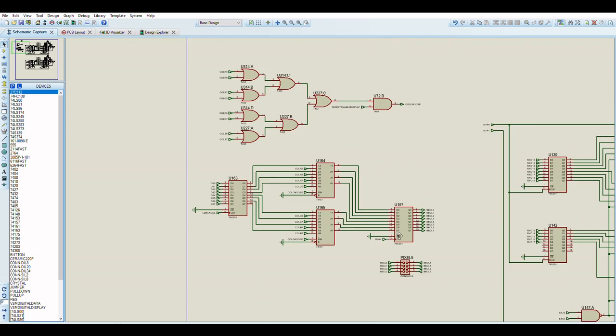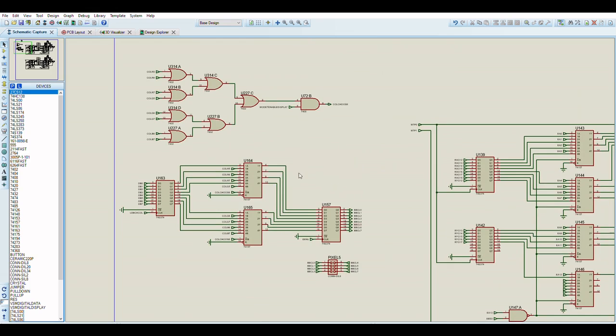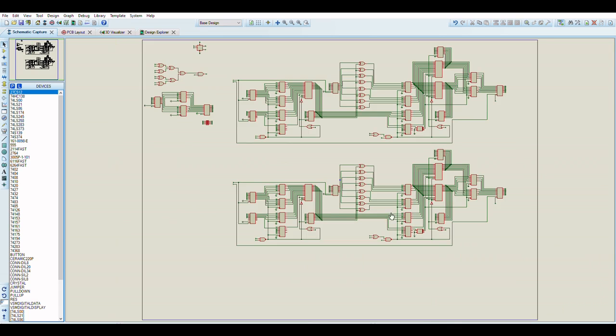Right? So this does a quick little transparency test. Transparency test is done here, but the output of that is used here to change whether or not the demuxer uses the calculated tile pixel color or the background pixel color, and then it goes and it gets latched finally into the output pixel latch here, which then goes to the header. So that's the mode 7 board.